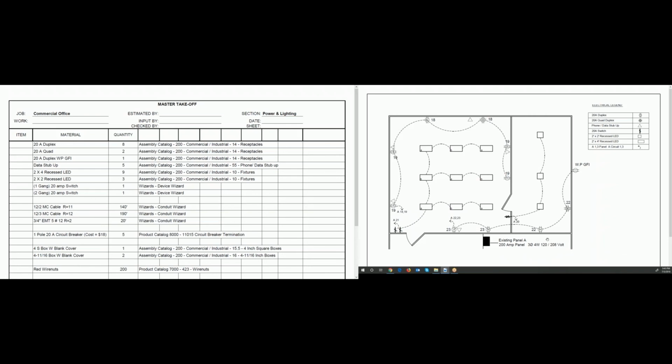Now, last but not least of my description with conduit takeoff here, my point is that you have a certain wiring method that you use when you're doing electrical projects for how you come out of the panel. In my experience in California, we can't come out of panels with MC cable, so we have to stub up out of the panel with 3/4.